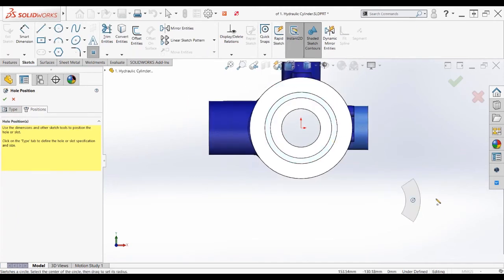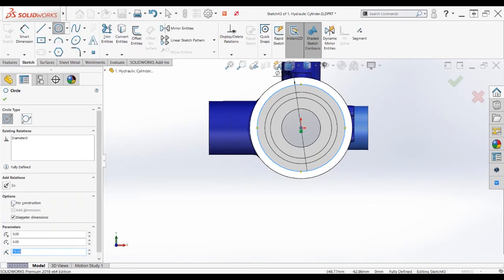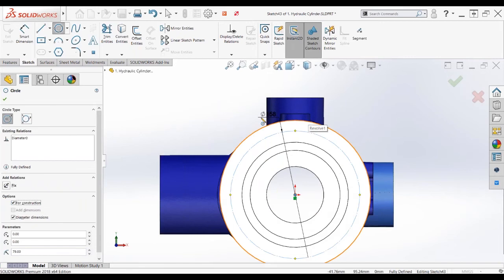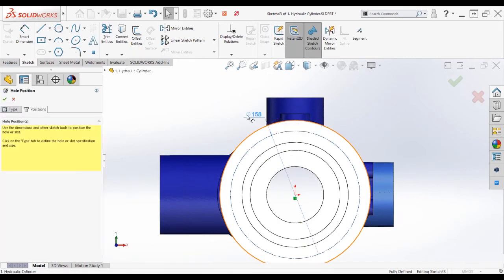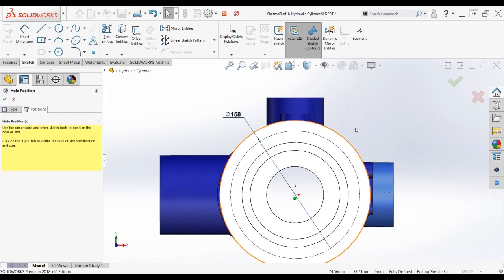Awesome, just like that. Use my mouse gestures to grab my circle. And as I make this circle, you can see the other option come into play. There's a nice input box for my dimension. So I already clicked on the origin there to locate the center of my circle. Now I can type in my dimension and we can see that SOLIDWORKS has smart dimensioned my entity for me based upon the drafting standard in my document template. Really handy, really awesome.